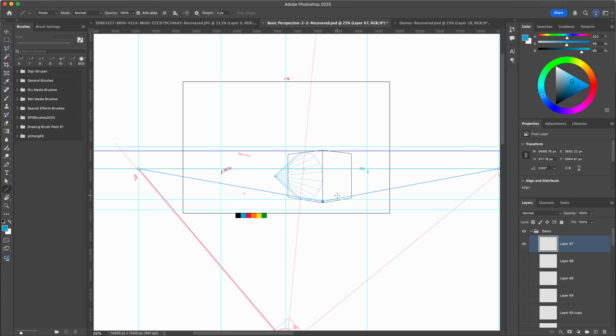Next, we're going to jump into doing blueprint plans of a vehicle, some of the concepts behind that, building out a bounding box for that, and then using the concepts of the measuring points and measuring lines to find accurate landmarks within those blueprints that we can then use to model a technical drawing with these tools.